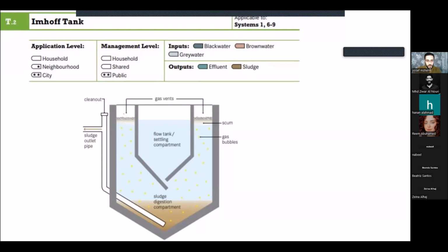complex. It's called Imhoff tank, which is basically, okay, we put a new layer of water or waste going through the center, and then it settles down and it goes to the main chamber where we have compressed air, where we can see the reaction happens here. Any remaining soap waste or oil, the scum, will go to the top. And every once in a while, we can also take the sludge and it goes to the next process.